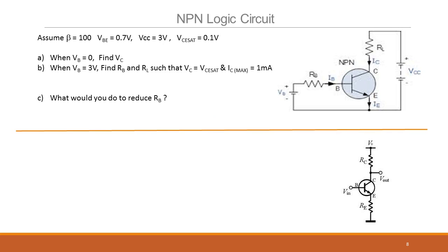Okay. Second problem. So this first problem dealt with biasing the transistor. Now the second problem is a little bit of a gain circuit. The same transistor, instead of an RB, we're now going to put an RE, a resistor in the emitter. We retain the RC. We call it RL, we call it RC here. And we call this port Vin and this Vout. Remember now the base emitter voltage is not the same as Vin. Base emitter voltage is Vin minus emitter current into RE. So that's a slight change in this circuit configuration.